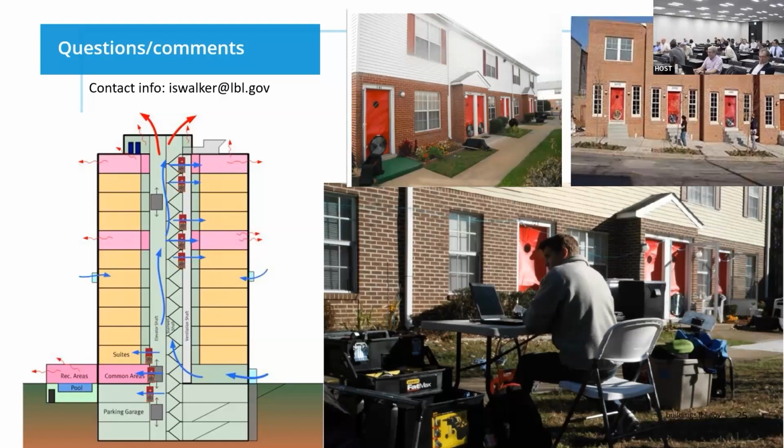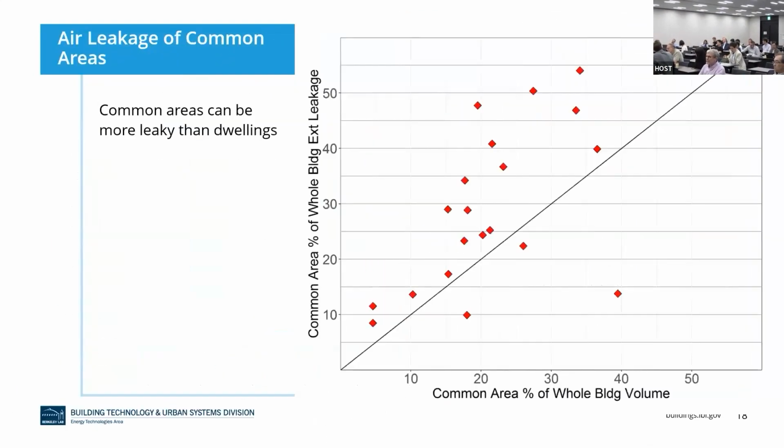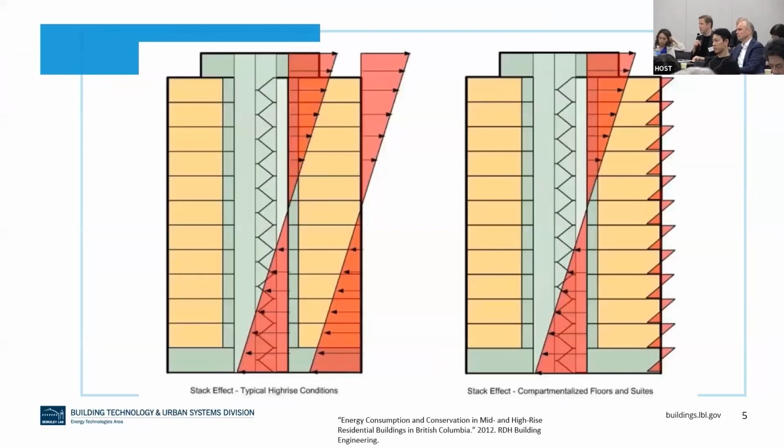I'm really interested in the finding that by just tightening the internal walls, you get a reduction in energy. If I was modeling, my initial assumption might be that the delta T between spaces was 0. So what's going on? I think it's mostly this: when you compartmentalize internally, you massively reduce the pressures across the building envelope. And if you massively reduce the pressures, you massively reduce the flows. So the total airflows for those buildings changed a lot when they sealed the interior partitions. So I think it's mostly this, Ben, is what we're seeing.